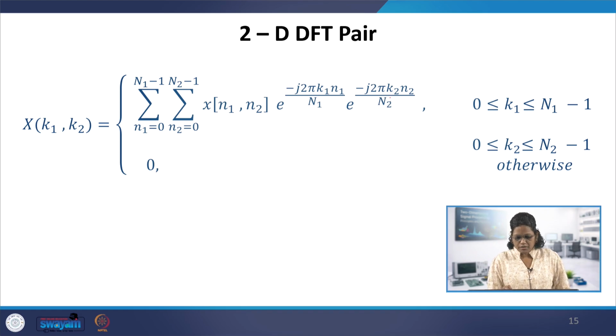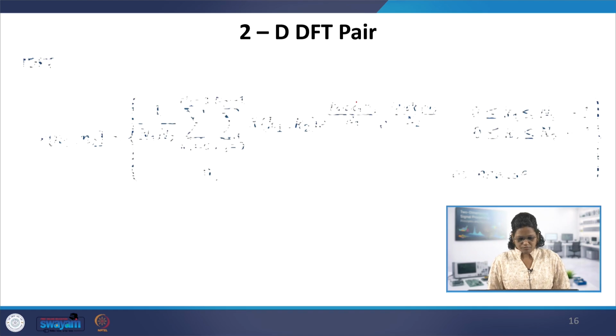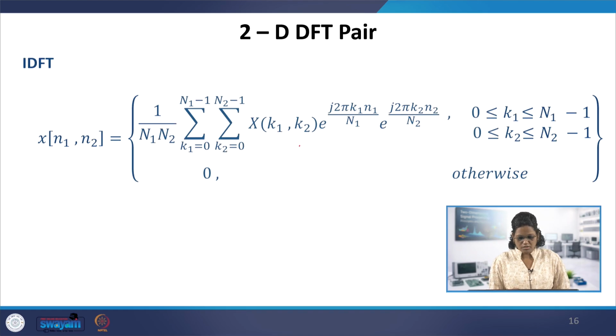We would now plot these two for the real and imaginary case. So the inverse DFT, using the coefficients, we can get back this sequence. But the thing is here, e power j 2 pi k1 n1 by N1 contains real and imaginary parts as well, whereas in the DCT it is only the real part.